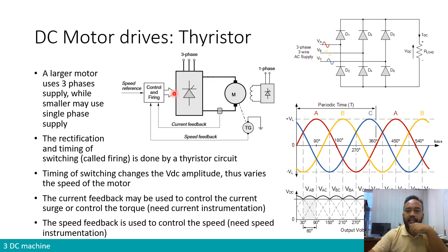And then with this thyristor circuitry, as we mentioned just now, we need to decide if we want to control the level of voltage. We control it by changing the moment in which we fire the thyristor. So in order to be able to control the thyristor, we will have a control circuit.